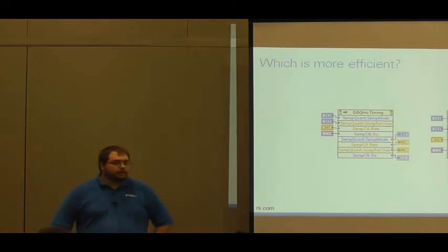So by default, LabVIEW is going to just execute property nodes in the order you've set them. And they're kind of unique. There are times where you may need to set one property before you read back or set another property.